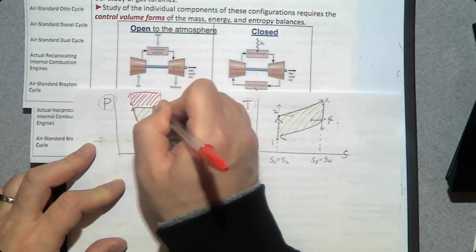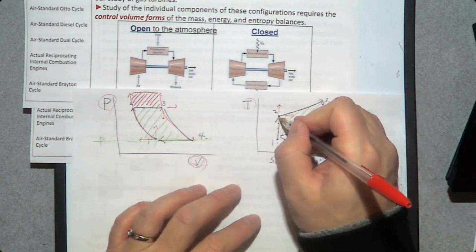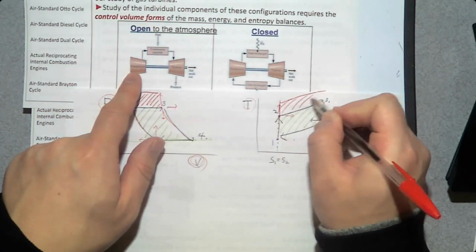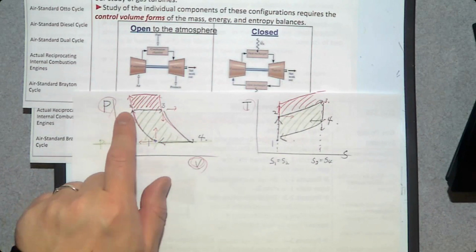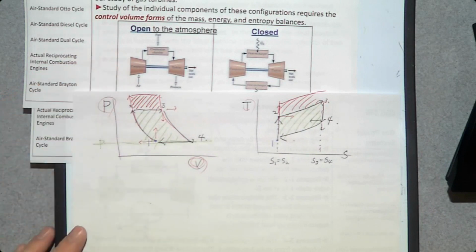So we are adding this much net power. So if we increase the pressure, which means that we compress more, then we can add this much power. So one of the key ways to increase the thermal efficiency of this gas turbine cycle, we are going to increase the pressure at the end of this compression process. So that's how we can improve the performance.